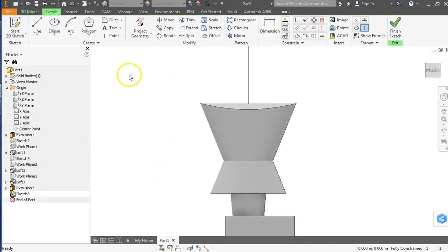Okay. And now I'll project geometry just in case for that top line. I want to make sure I can choose and reference that, and I even want to make sure I find the middle. So I'm going to grab the point tool and slide slowly across there until I find the point-to-point constraint. You can see the little gray box down and right of my cursor. The green dots don't always appear, so pay attention to that gray box because that is something you should be able to see. Okay, I'm going to click right there so I have a point referencing the middle.